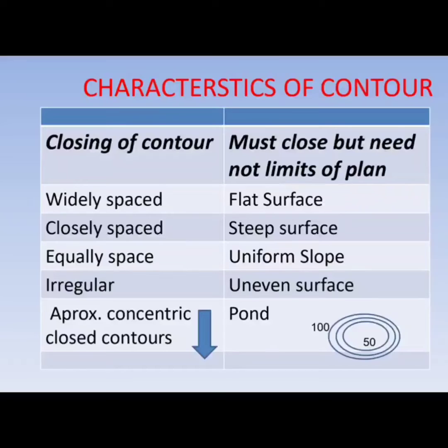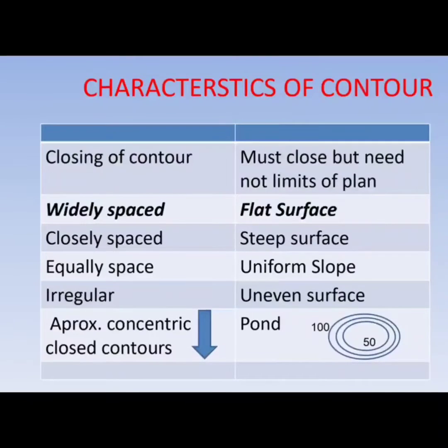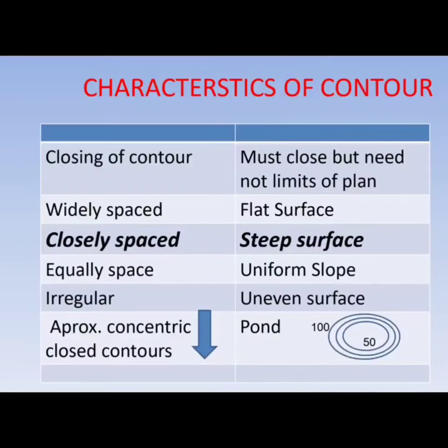Characteristics of a contour. Contours must close, but need not close within the limits of a plane. Widely spaced contours indicate a flat surface. Closely spaced contours indicate a steep surface